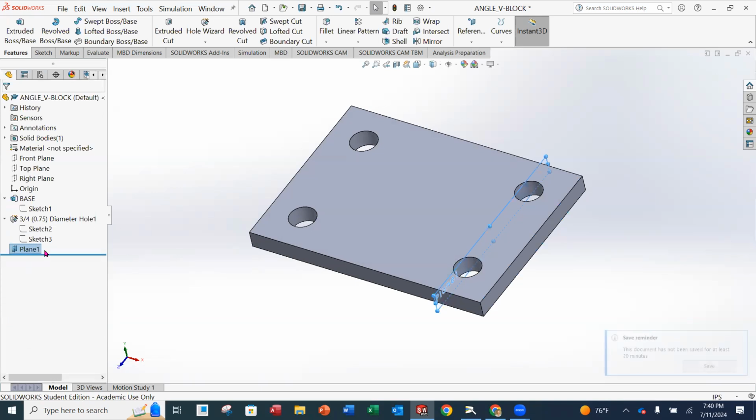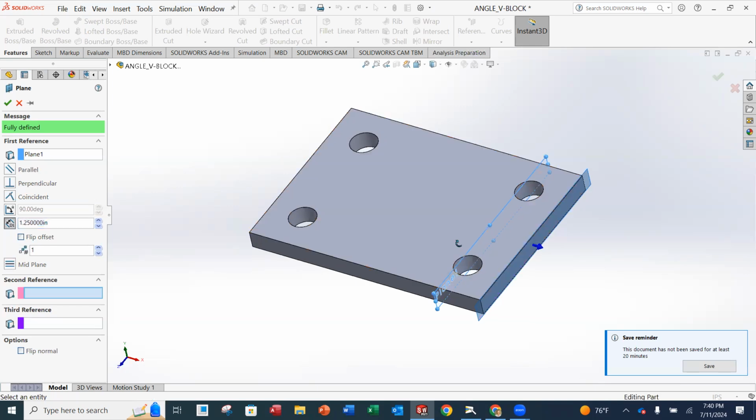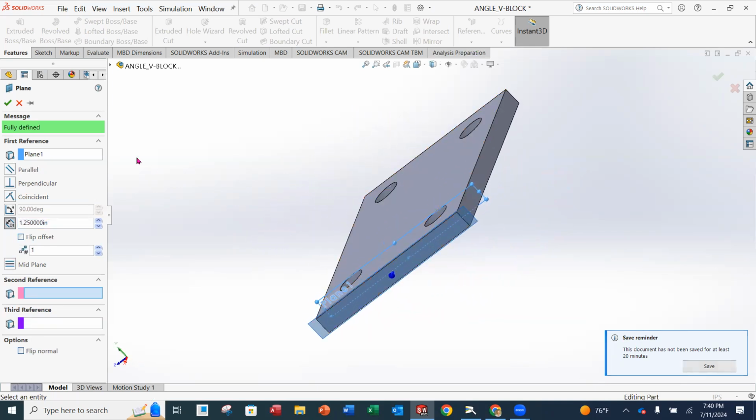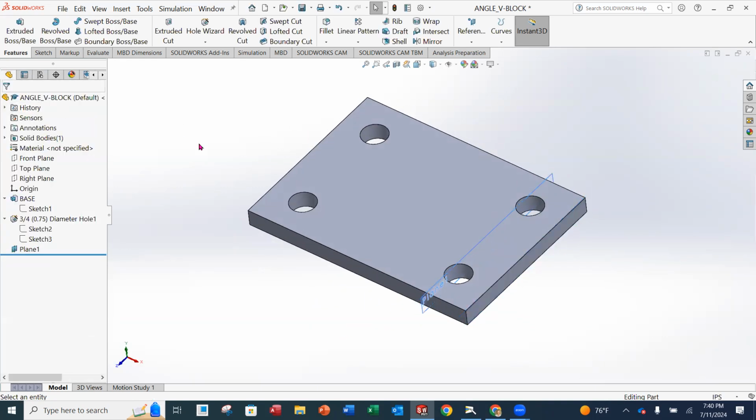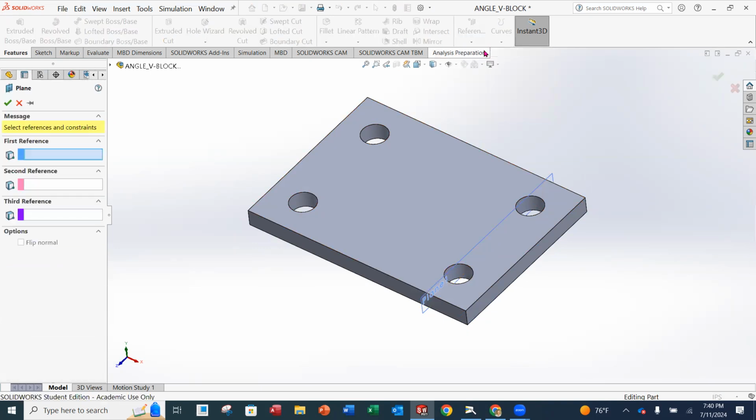That's plane number 1. I'm going to do another plane. So Reference Geometry, Plane, and we're going to go back from here. Oopsie, you know what? I had it selected, my fault. Let me X out of here, unselect, so we're not on that plane. I think that's what I had. Do this plane. Okay. Yeah.